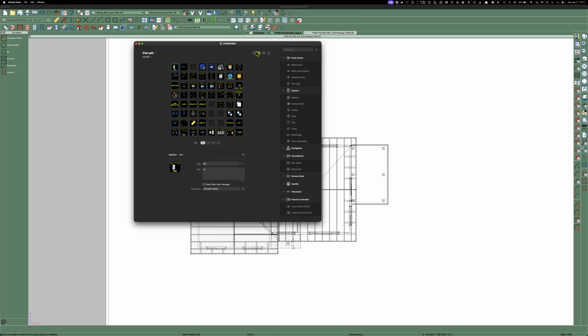Yeah, so like, here you go, point-to-point move. Part of my naming convention that works for me is I use SketchUp and I use Chief. I primarily use Chief, and then I use SketchUp for really accurate 3D models, and usually details. So in point-to-point move, I use MM. I just hit MM on the keyboard because in SketchUp, M is the move command. Just like center. Center is CC. I don't think there's an equivalent in SketchUp, but some of these things are just too easy to type out on your keyboard without having to try to remember too much.